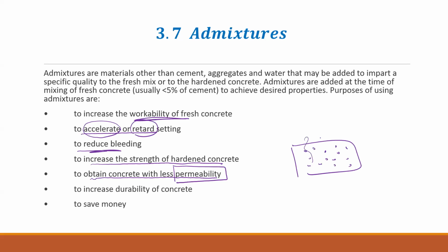And also it will damage the concrete, because if the concrete is permeable, water can move through the concrete and it will affect the durability. So we can add some tiny materials, additives, to control this permeability. However, in some situations, we need to have a certain amount of voids in a concrete. We will learn that when we do the concrete mix design.